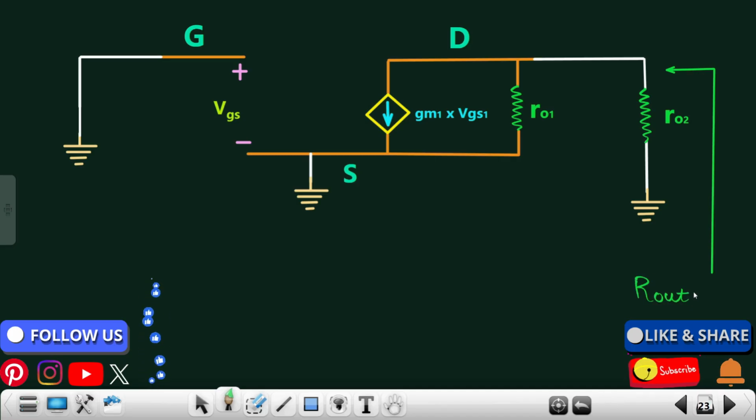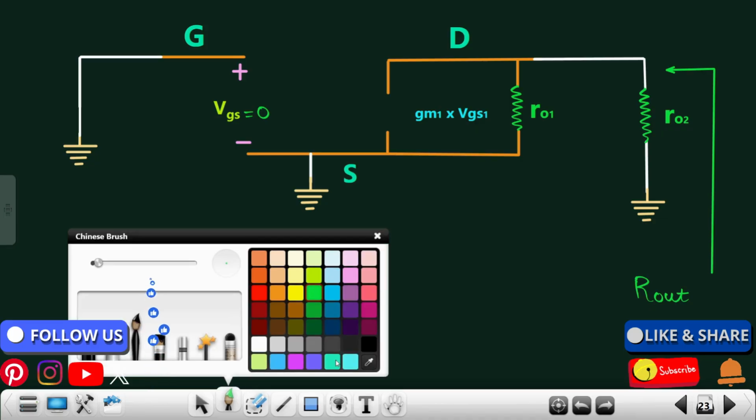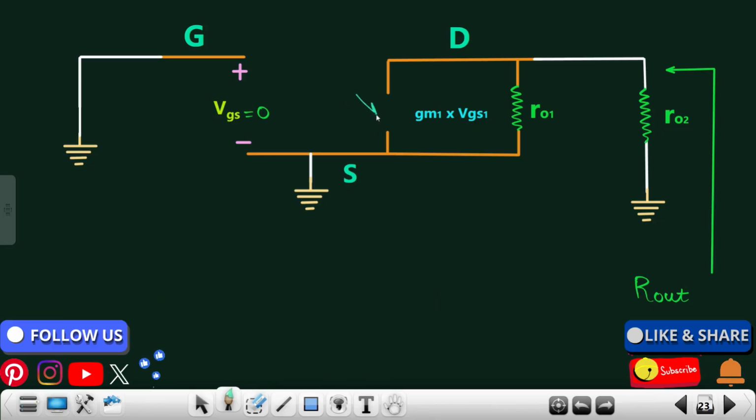So what is my Rout? If you look at this particular point, my input is grounded. So my VGS will be straight away 0, and if my VGS is 0, the output impedance will be RO1 parallel with RO2. Why? Because this particular part will act as an open circuit.